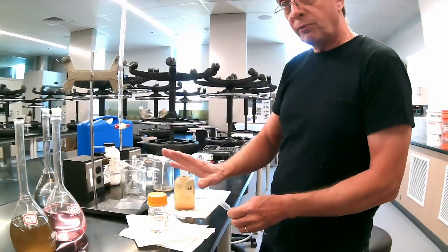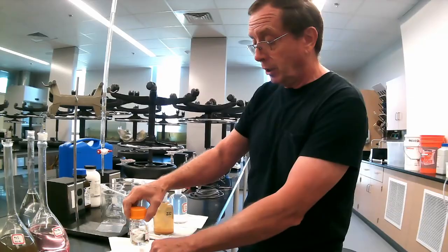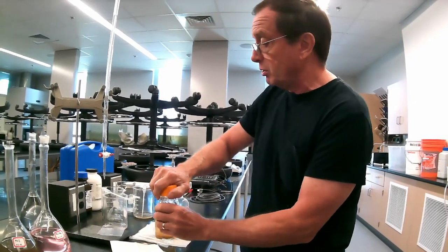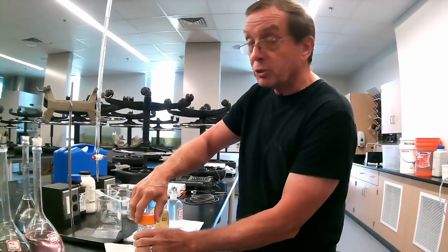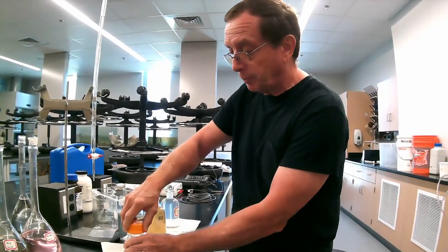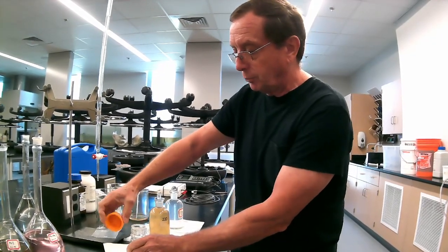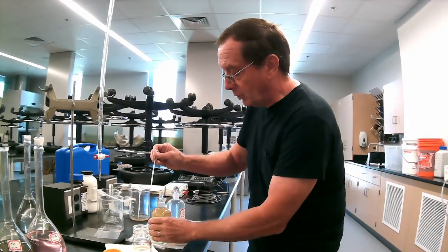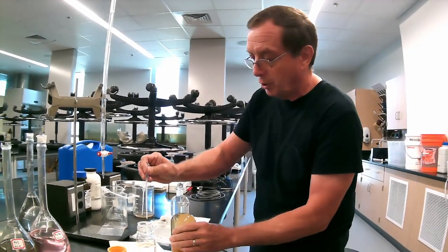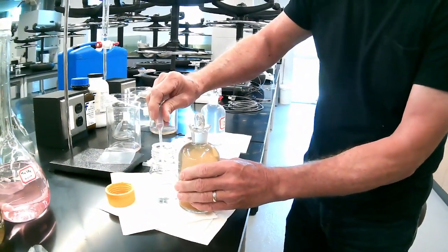Once the sample is fixed, no more oxygen can get into it, and that's the key here. You can set it in the refrigerator for a month or so if you don't have time to titrate it when you collect it. We usually titrate soon after we're done with the flocculant stage. Again, you don't have to measure out too much for how that works.